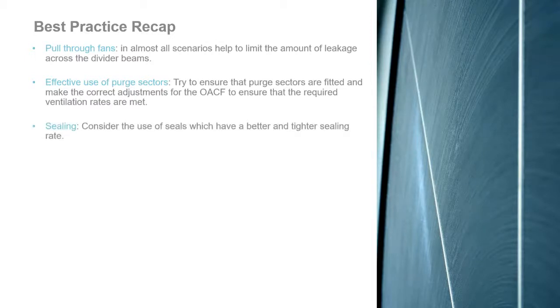Consider the seals. Sadly, I know through many years of working with heat exchangers, the number of calls we get to replace seals is actually quite low. But they are a perishable item as well, and over time they will wear down. So start to look a little bit more at the seals on the rotors and the alignment. If you can see gaps in the alignment, then you know that the seal is not working at that particular point. So it's a good chance to change and to check the alignment of the rotor. So again, corrective maintenance, these regular checks on sealing systems and rotor alignment.